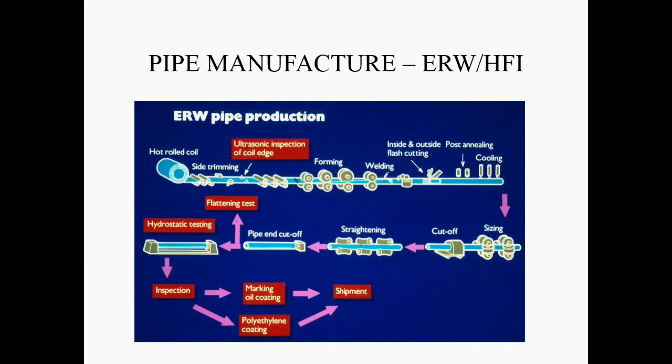You then have to unroll that coil and straighten out the coil and trim the edges, because you want them to be perfect. When you actually make it into a tube, they've got to line up perfectly. So there's a lot of stuff there to do that. And these rollers are driven at different speeds. These ones are slow, these ones are faster. So we stretch the material and get rid of the wrinkles a little bit in this stage.